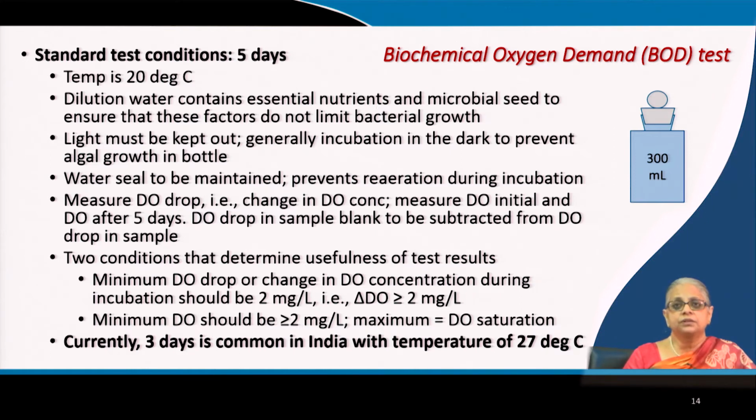So that is the first thing. The second thing is, if you're dealing with industrial wastewater, let's say, like I said, a pesticide. So let's say we have wastewater from a pesticide manufacturing plant. Now this toxic material is not going to contain any microbes to begin with. So you may have to add microbial seed to ensure that there is at least a good initial bacterial population.